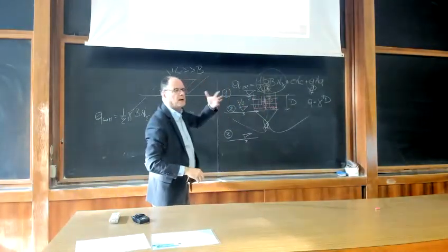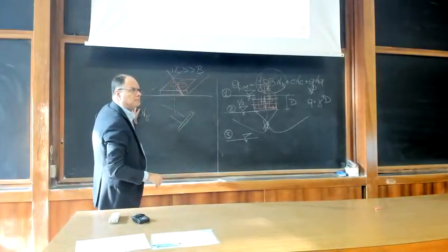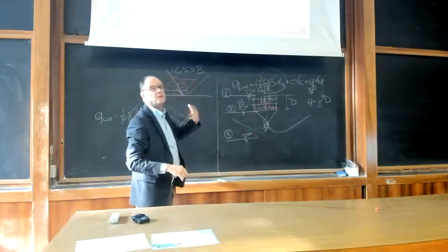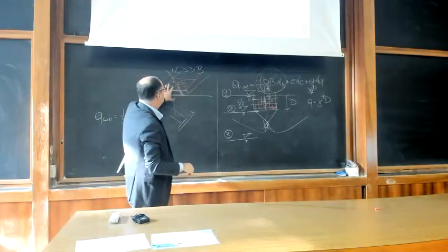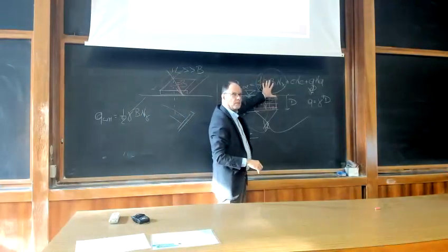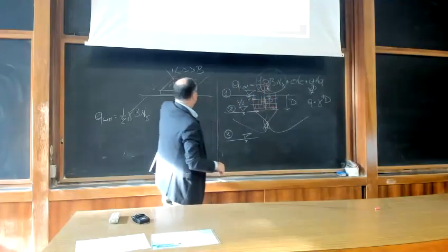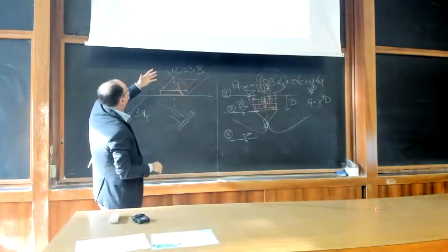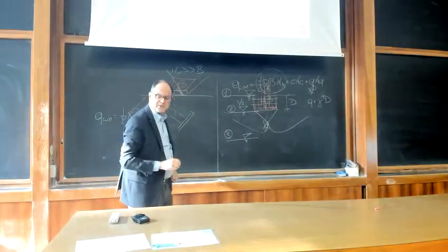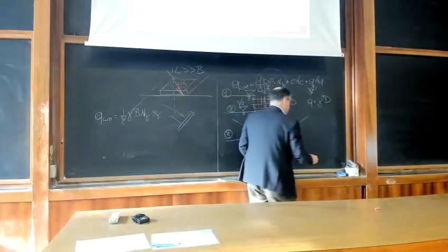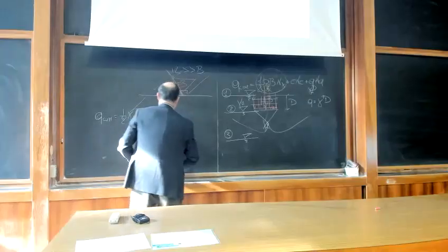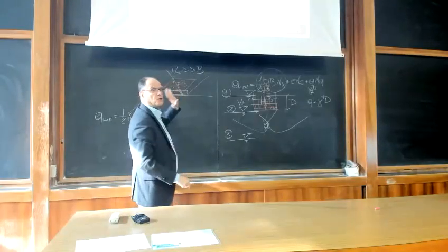And then you multiply this term, but also all the other terms, by correction factors, which take into account all these deviations from this starting formula for considering other situations. So you will have an S gamma, which is called a shape factor, which considers the case in which the shape of the footing is not a strip footing.